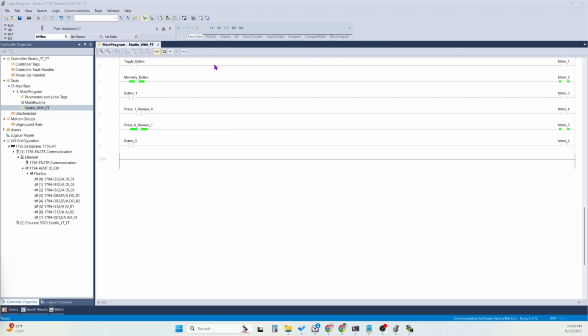If you are not using Emulate, then it is two. It's a driver, so for Ethernet communication and other communication between FactoryTalk View Studio and Studio 5000, you have to use a driver, like a car driver, taxi driver, and bike driver.